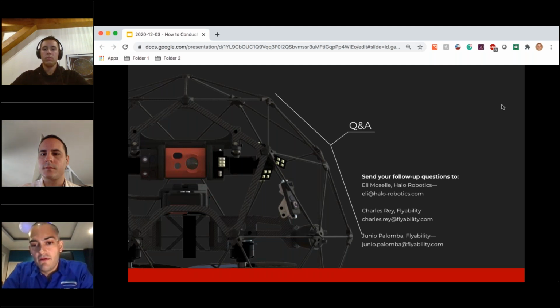The drone is still safe to operate, but it reduces the battery time that we plan. Where typically a Helios 2 battery will give you 11 minutes of total flight time, we budget 8 minutes per battery. You would reduce the flight time by about a half when you're working at high altitude.